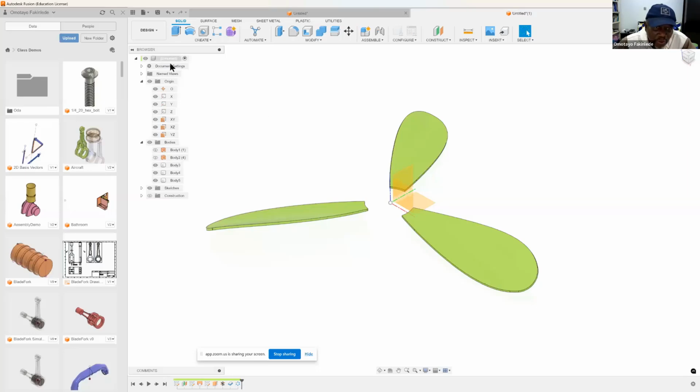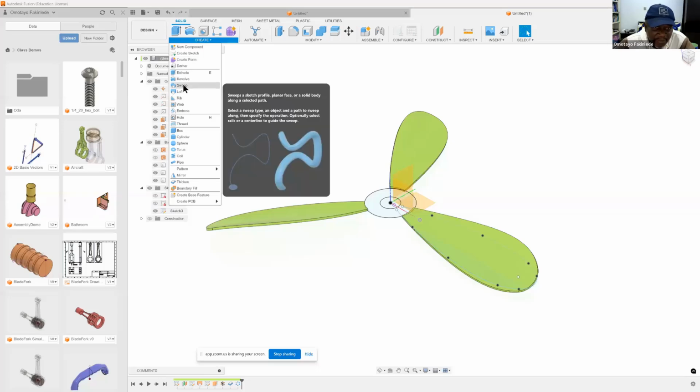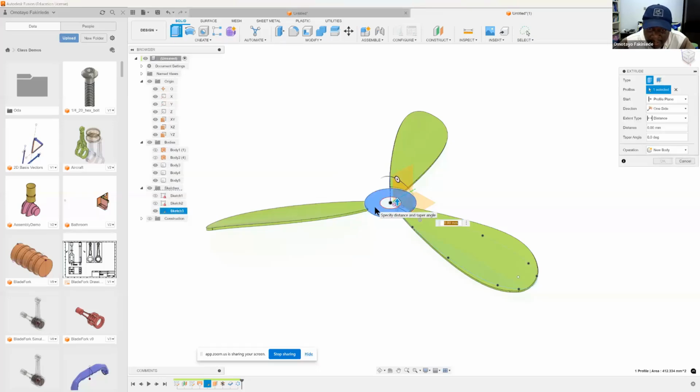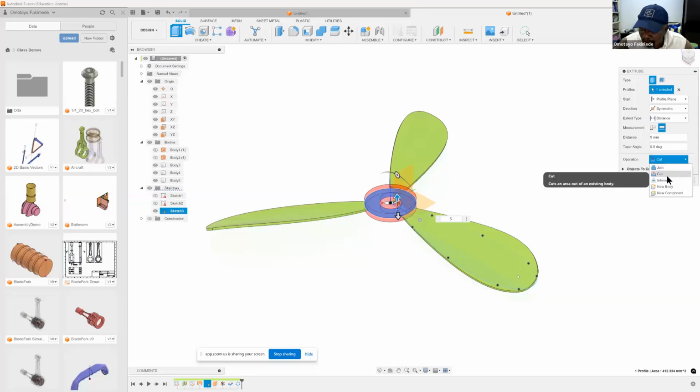So the next thing I want to do is to go back to our sketches. In sketch 3, I am in a position to now create a rotor and a stator. Normally in a real file, you create only a rotor there, but I'm going to create a rotor and a stator because of the assembly process. So I can create an extrusion in the solid making body now. I created an extrude here, and I said I want that extrude to be symmetric, a total thickness of 5 units, and it is a new body. It's not a cut, but a new body.